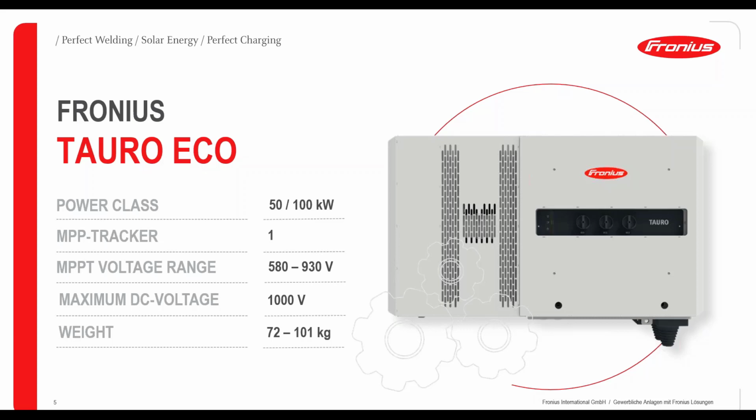A few data about the new Fronius Tauro Eco device. It's coming in two power classes: a 50 or 100 kilowatt device. It looks the same, like we can see here on the right side. It just has two power stacks inside with the 100 kW and one power stack with the 50 kW device. Both of them have one MPP tracker, and the MPP voltage range is from 580 up to 930 volt DC. The maximum, the same as with all other Fronius inverters, is 1000 volt DC. The weight depends on the power class, of course. It's between 72 and 101 kilogram. So therefore we need at least 3 people, let's say.